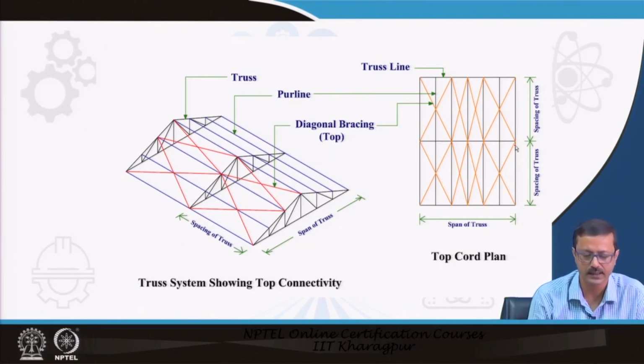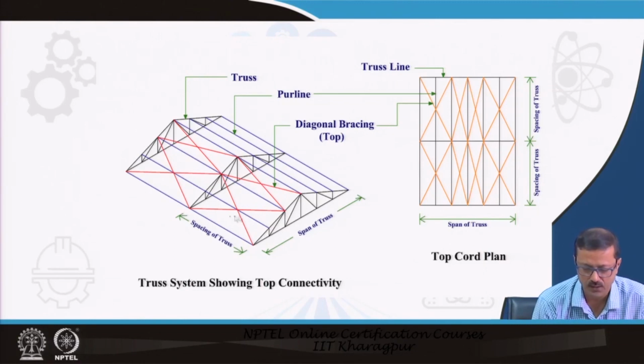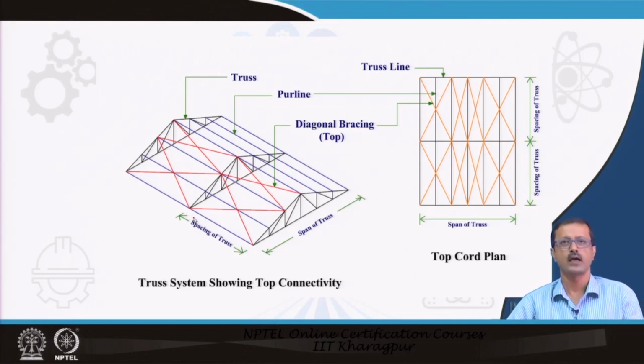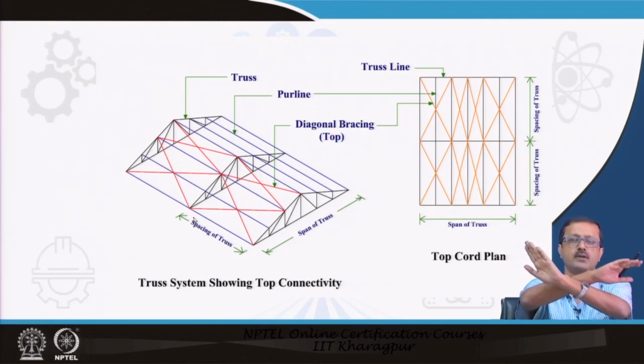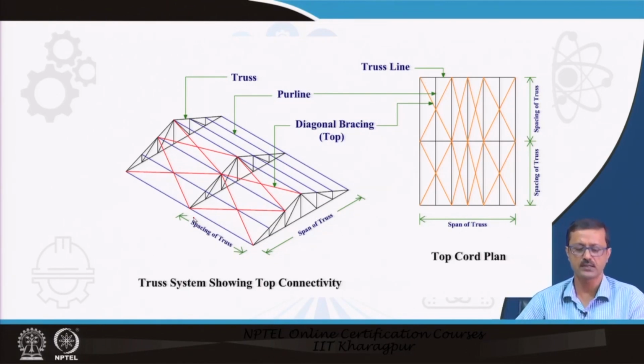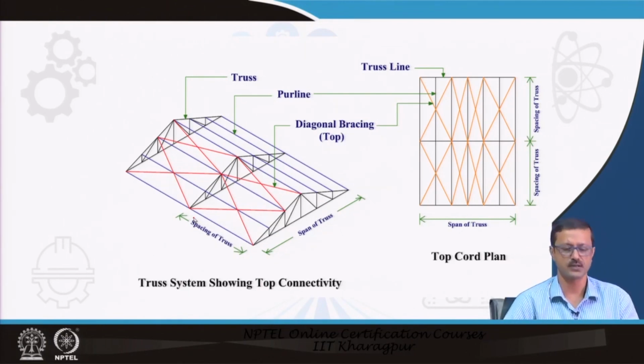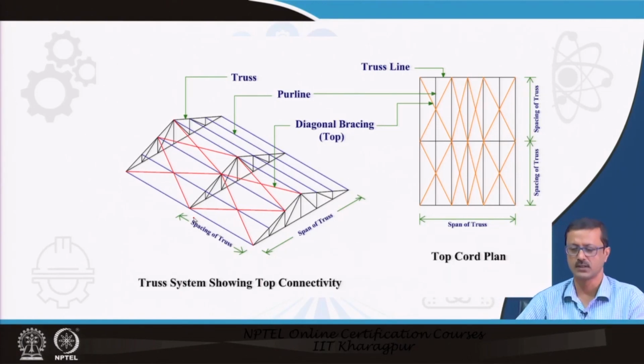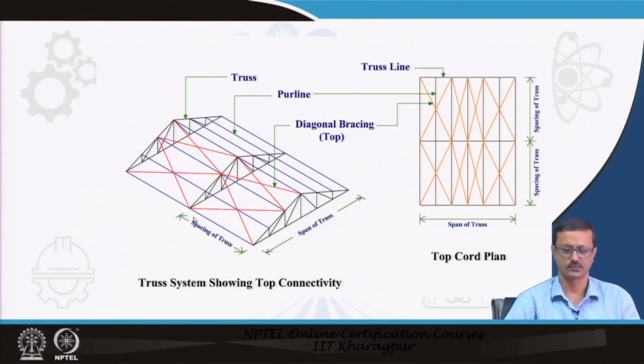So, see the red lines, those are the bracings, the connecting members diagonally from one truss to another truss, and they also connect from the nodal points. So, in addition to the purlin, we provide a kind of diagonal bracing, and how many bracings and what the size of the bracing will be has to be found out from the load distribution and mathematical computation.